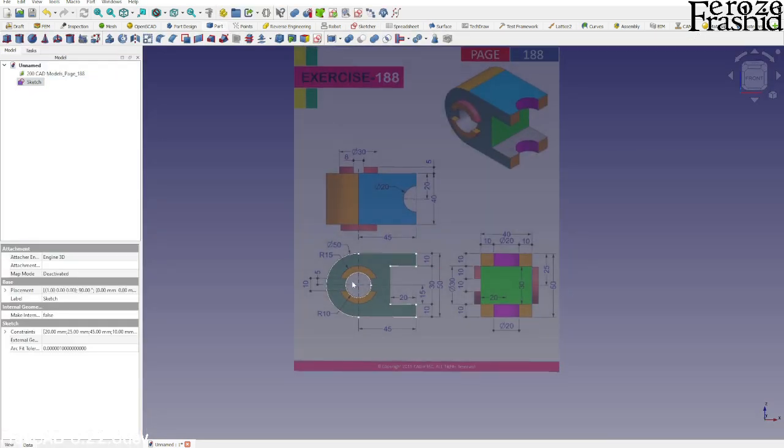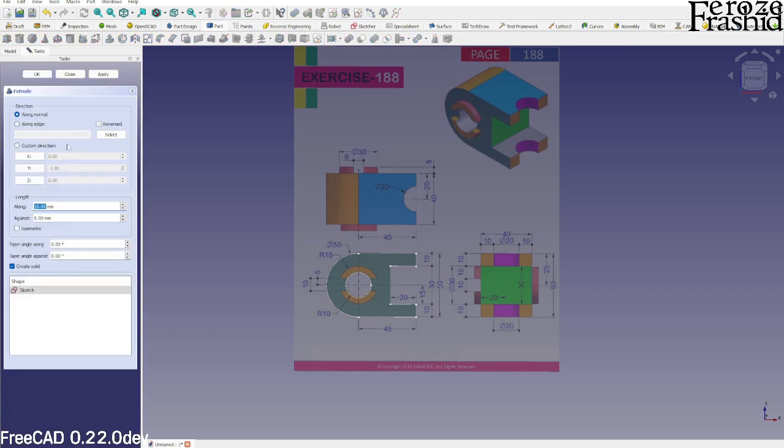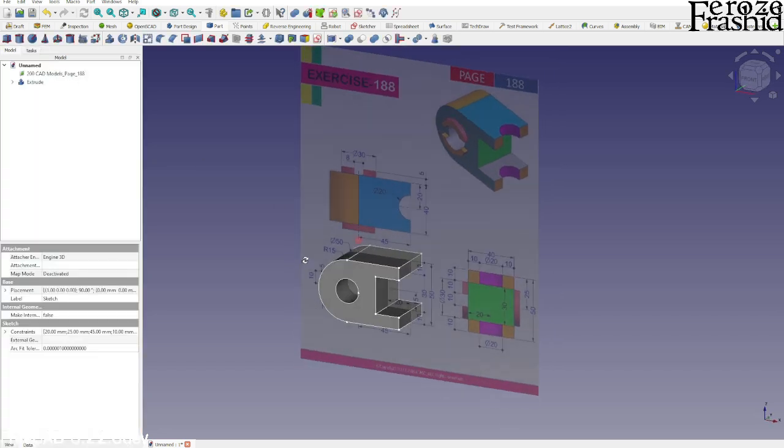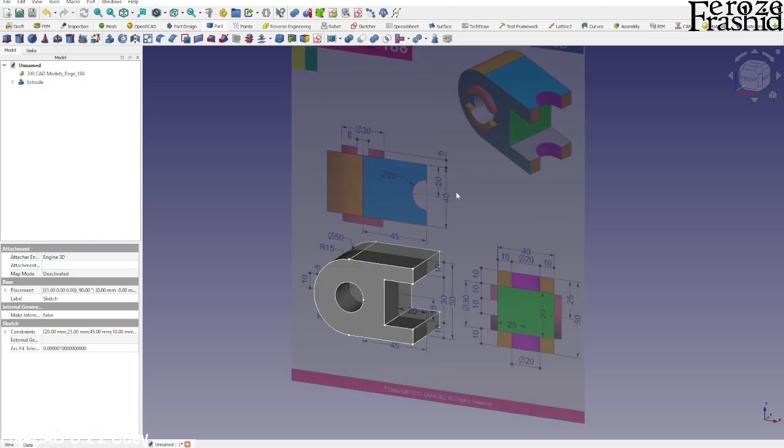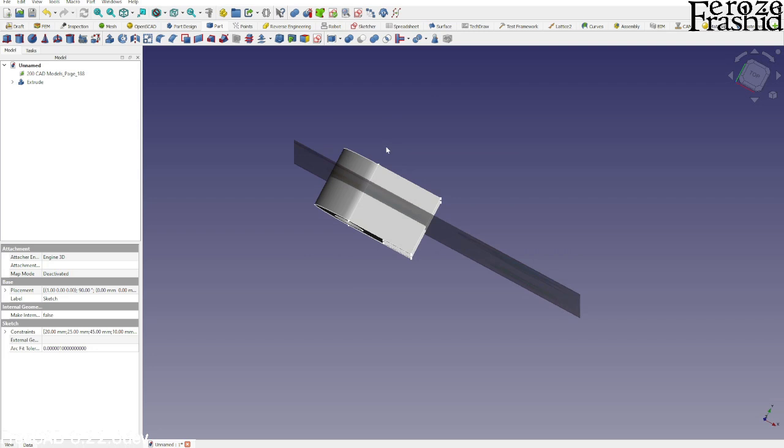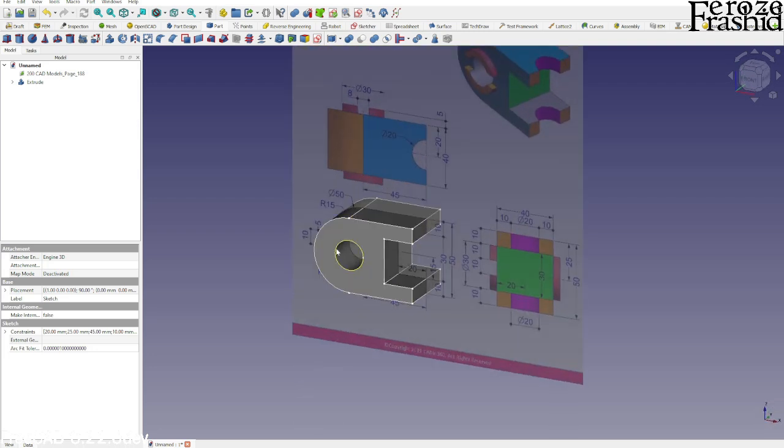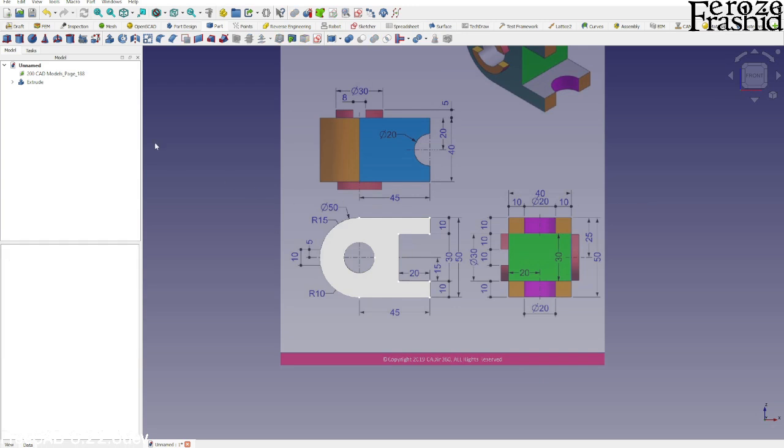All right, considering this sketch is in the middle, we will have to extrude that 40 millimeter and make it symmetric by the axis. So that's a major part done. And then I want to say, take care of this color. On one side, it's got an indentation in there. Another side, it looks like it's solid one. So it doesn't matter which side it is, but looking from this top view, looks like this end will have that indentation and this side will be solid. Either way, we will do that with a tube.